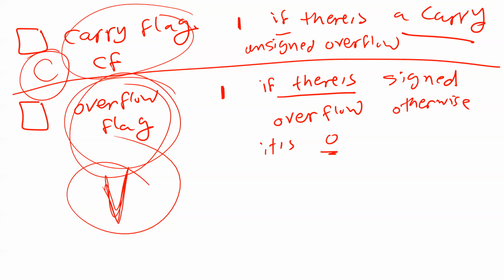You understand what I'm saying? That's why you are going to get both of them. Even if your numbers are unsigned, you will get V. The computer doesn't know, okay? You are the one who knows. That's why it's going to give you the two answers. So now you understand what I mean by overflow. Now you should understand that if you do addition and you want to check if there is overflow or not, which flag you have to check, the carry flag or the overflow flag.